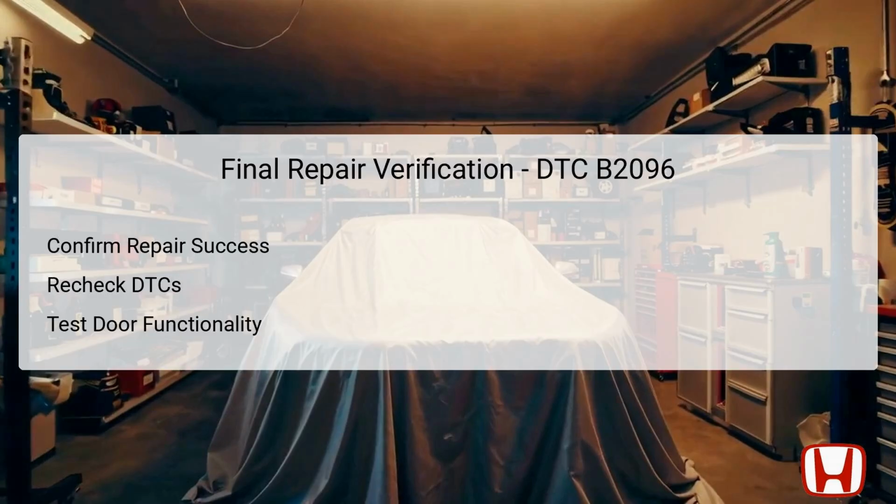After completing repairs associated with DTC B2096, it is crucial to conduct a final verification to ensure that all issues have been resolved. Begin by rechecking the DTCs using the HDS to confirm that no current errors are present. If the DTC clears successfully, this indicates that the repairs made were effective. However, even after clearing codes, testing the door's functionality is equally important.